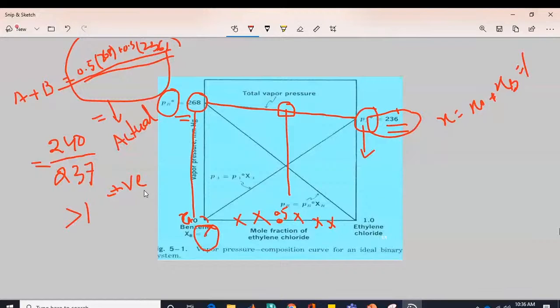Let us talk about simple distillation first. It is a process of converting a single constituent from a liquid mixture into a vapor, transferring the vapor to another place, and recovering the liquid by condensing the vapor, usually by allowing it to come in contact with a cold surface. This process is known as differential distillation. Distillation is based on the difference in volatilities and vapor pressures of the components of the mixture. So that's one of the simple concepts about simple distillation.